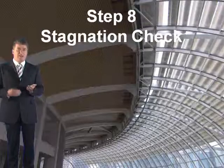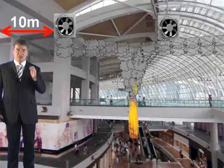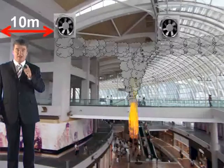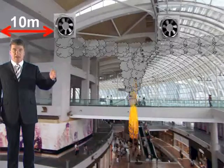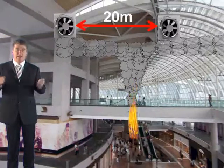Well, before you decide this, you've got to carry out the stagnation check, which is step 8. This only applies to natural, but we are going for natural. And what it says is, the maximum distance from the edge of a building to a ventilator is 10 metres, and they can't be more than 20 metres apart.